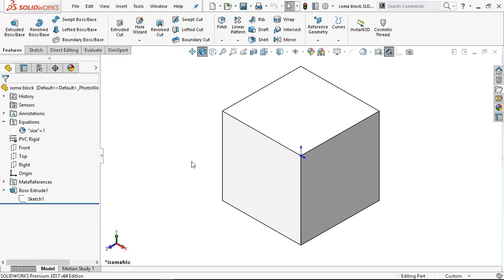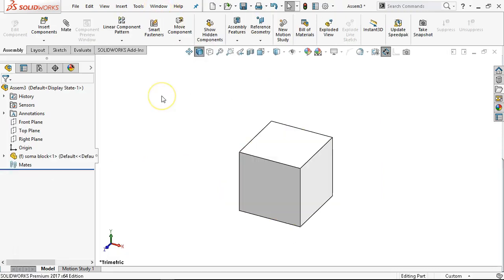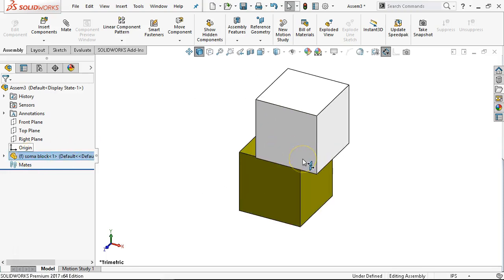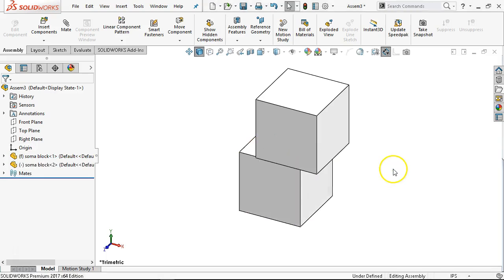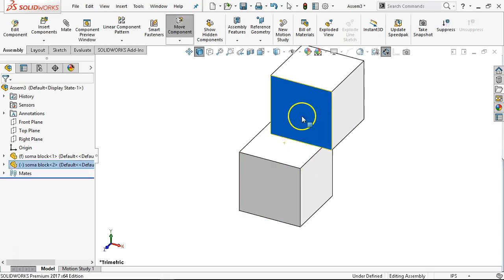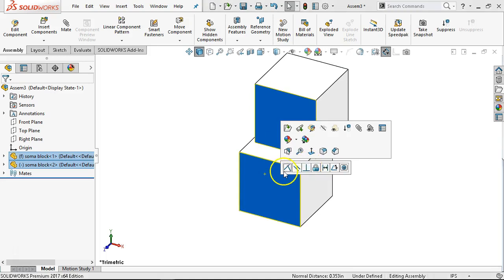So as long as the naming is, and these being the same part, we have at least a chance of it working. What this is going to do is, as I drag to that face, I'm automatic coincident, and it picks up the coincident. And then, okay, what happened to my secondary and tertiary? So those I still have to go ahead and add.